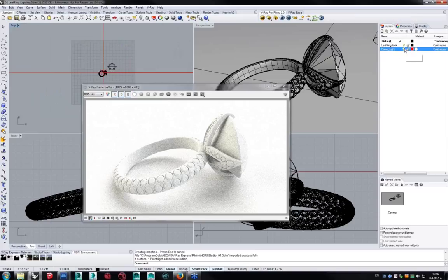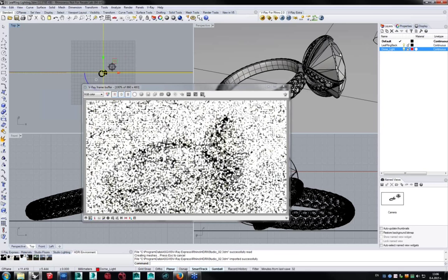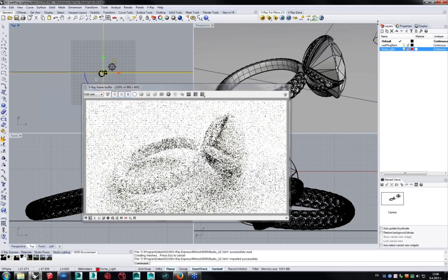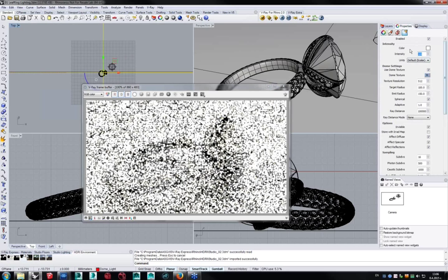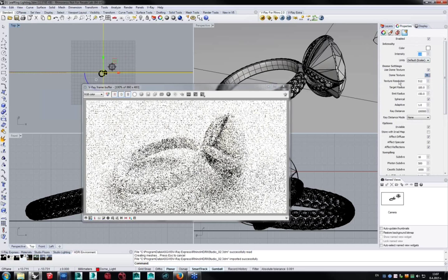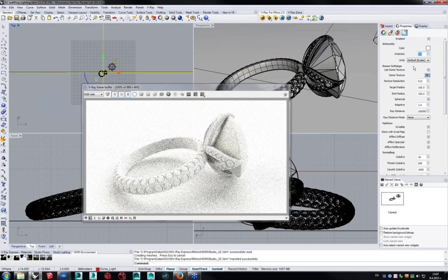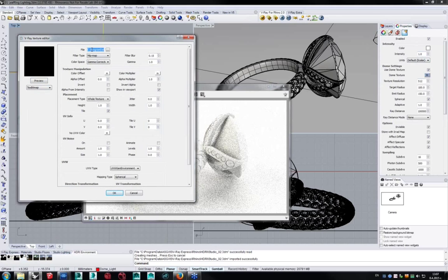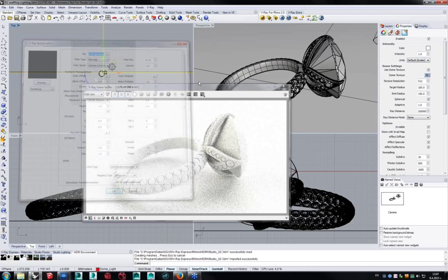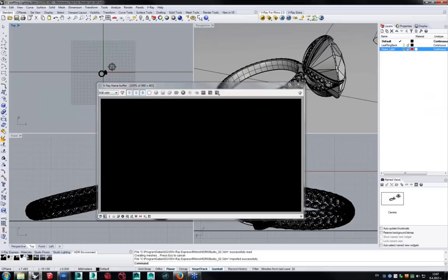The cool thing is that it's over here inside a new layer, so I can turn it off. There we go, and I can create a new one with a completely different setup. So this is something that you can easily use. So let's lower the intensity, and not only can you use these all the time to do testing or final quality renderings, but you can also tweak them. So for example, this one has an HDRI, a studio setup of an HDRI plugged inside the actual dome light. So this is really handy to use. So let's turn it off again.